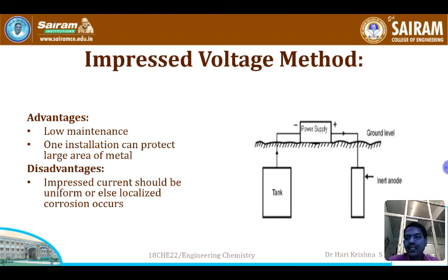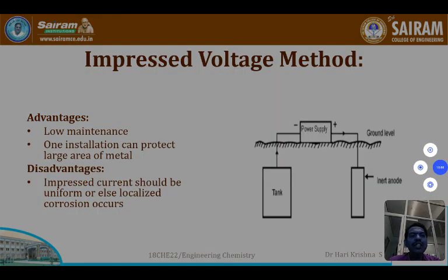Advantages: low maintenance, it is a one-time installation, and it can protect a large area. As I discussed earlier, the major disadvantage is that the impressed current should be uniform, or else localized corrosion will occur. Thank you.